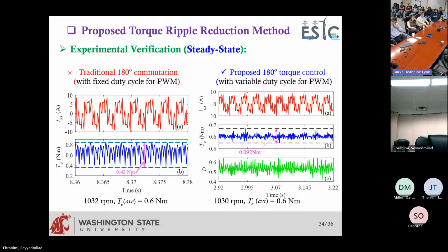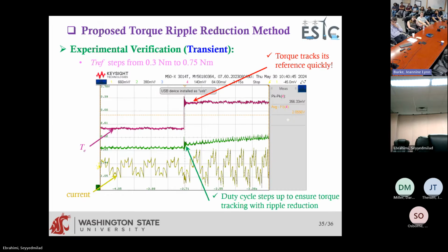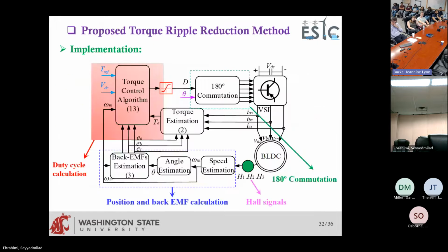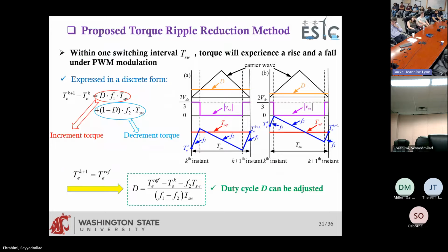Right, but you did derive the torque expression, like the derivative of the torque. Why is the reason not going the linear controls way, like formulating a frequency model or transfer function and then trying to fit a PI controller for this because you have the derivative of your torque? Yeah, you don't need any PI controller here. You can, but you don't need it here, because it makes things simpler when you want to load everything into your microcontroller.